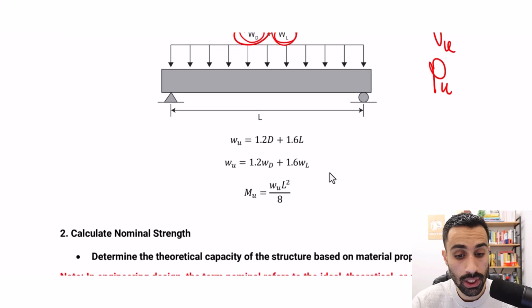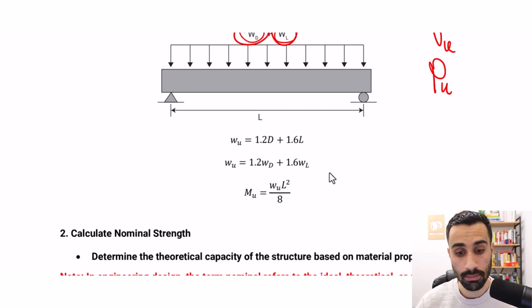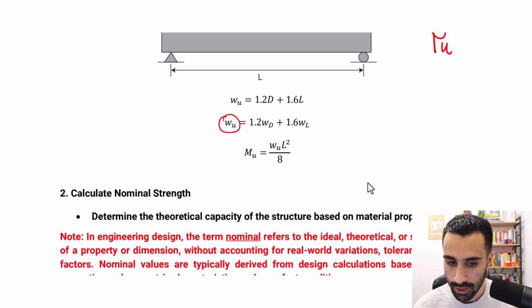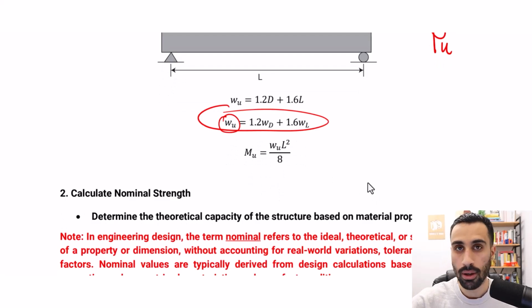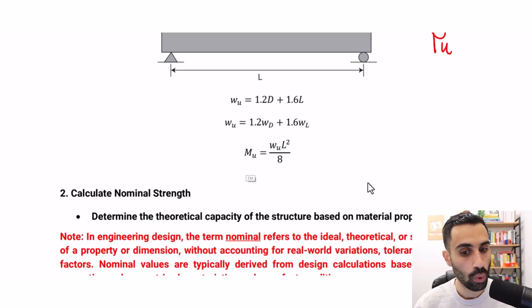They're both distributed loads, so I'm just going to substitute that in there and then calculate the ultimate distributed load. So here we're overestimating the load still, but it's distributed loads. That's fine. We're overestimating them using these load combinations, LRFD load combinations. Then what I can do is, with this calculated, I accounted for the load combinations. That's done with. I can then get the ultimate moment.